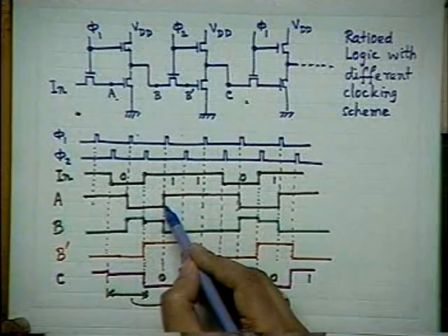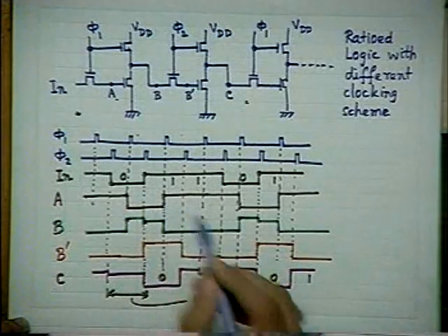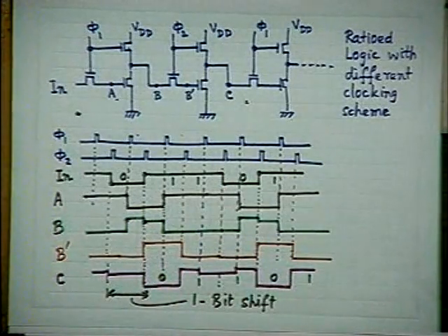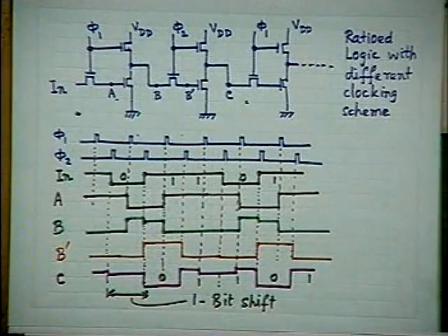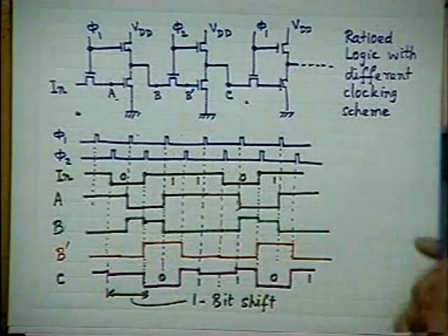I have not shown anywhere the charging and discharging time. In fact, I have shown sharp rises and falls everywhere. It is actually a very simplistic diagram. Let me tell you that whenever we draw timing waveforms, we usually do not show the so-called charging and discharging time, the on and off times. But these are very important. You will always find the signals delayed a little with respect to the clock because of the delays involved in the data path. That has to be remembered. But we have not shown it here intentionally. There is no harm; you can include it there.